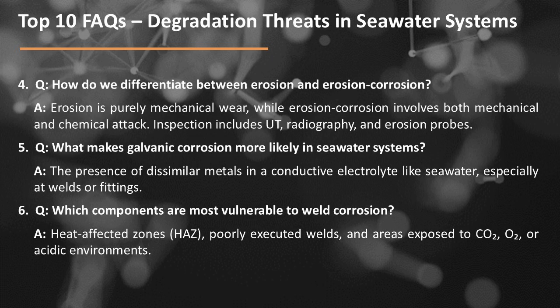Question number 4. How do we differentiate between erosion and erosion corrosion? Answer: erosion is purely mechanical wear, while erosion corrosion involves both mechanical and chemical attack. Inspection includes UT, radiography, and erosion probes.